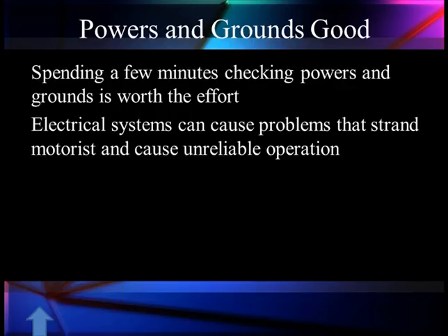Powers and grounds are good. Spending a few minutes here, checking parasitic draw and all the electrical system, is really important. Remember, the electrical system can cause problems that strand the motors and cause very unreliable operation.